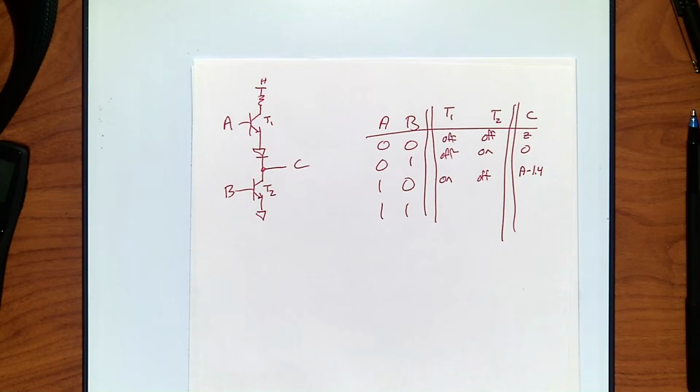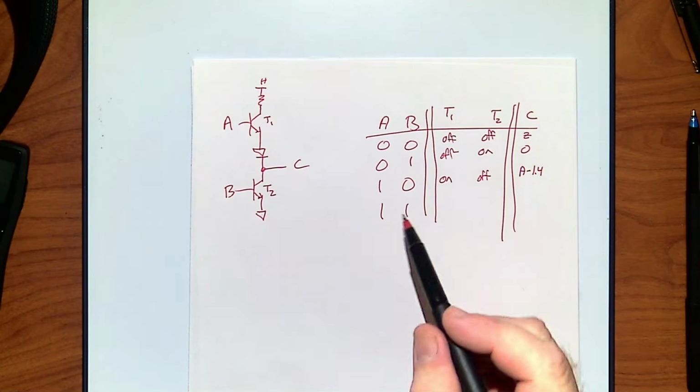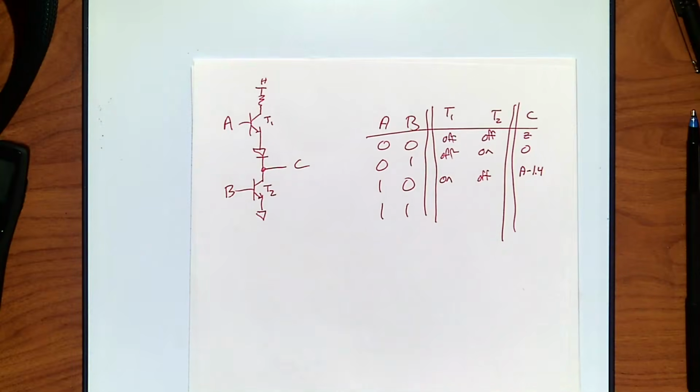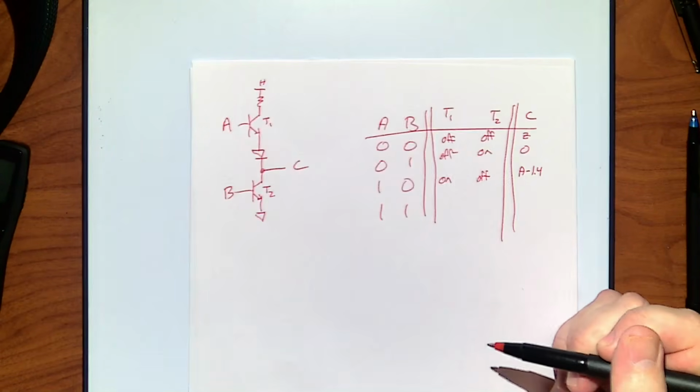TTL logic, depending on the particular version of TTL logic you have, if it's above 3.5 volts, is considered true. Depending on the type of TTL logic you have, above 2.5 could be considered true. So I'm still in the true zone, and that's a fine output. And this is actually why that 3.5 comes in, because it could have been a little less than 5, so you usually call 3.4 or 3.5 good, to allow for this zone.